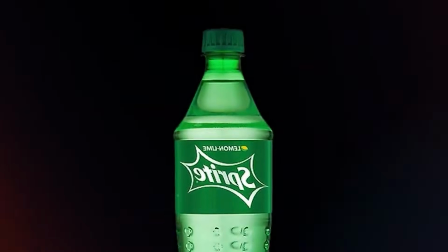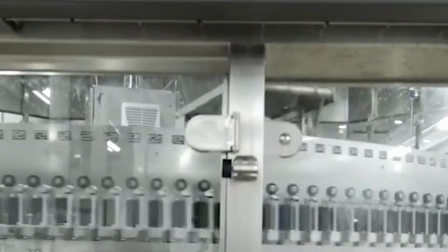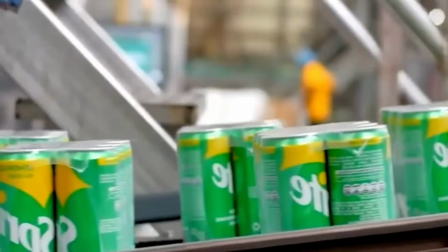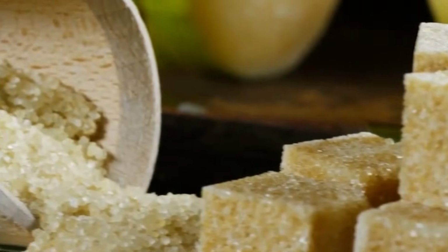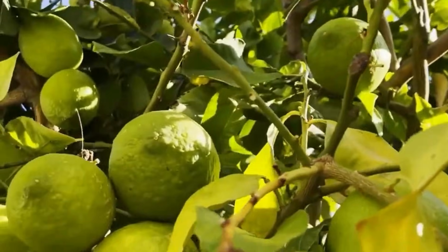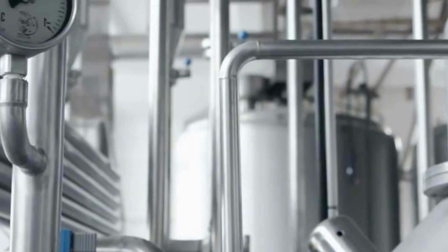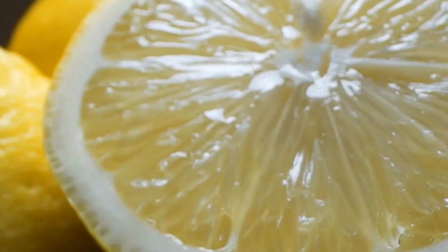Packaged units are routed to case packing stations. Here, automatic erectors construct corrugated cases from flat blanks using glue or tape. Robotic loaders with vacuum end effectors pick up groups of bottles or cans and place them into the open cases in pre-programmed formations. The filled cases are sealed at the top using either hot melt adhesive applicators or pressure-sensitive tape dispensers. Cases proceed to palletization.